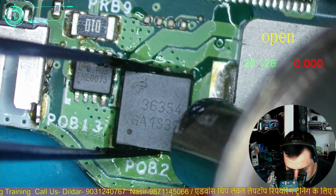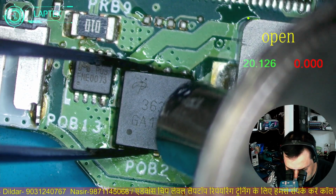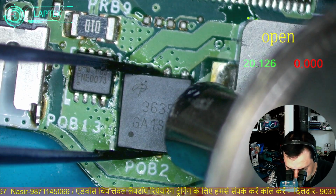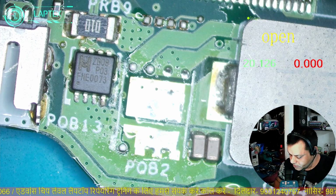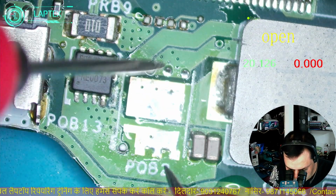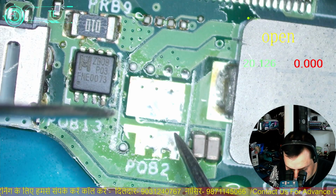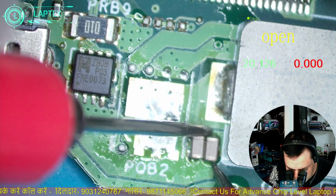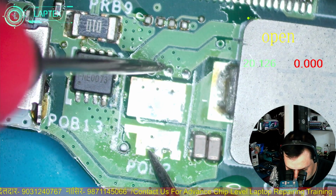Three six three five four, dual N channel MOSFET. Shorting must be removed. After removing it, if it is still there, it means it is not short here, somewhere else shorting is there. So we have to keep on finding.